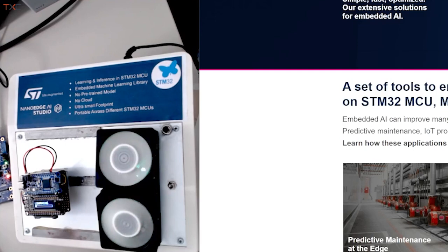So you can see on the screen here, we are entering a learning phase inside the microcontroller. During that phase, the main program is collecting vibration data sets from the accelerometer and sending those locally inside the main program to a dedicated AI library.